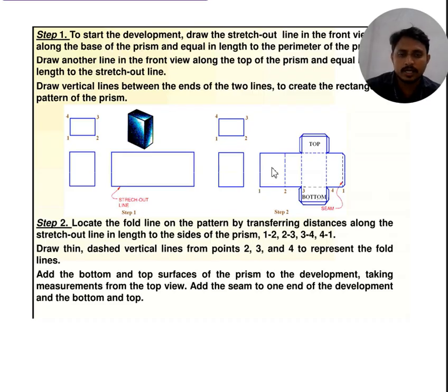See now how to draw step 2, or the second stage. First stage, how to draw. We have a square shape given, each side for example 3 centimeters, that is 30 mm. So draw each side 3 centimeters. If it is a front view, draw it above the reference line.